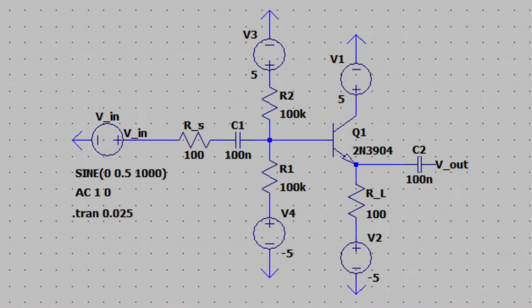For my schematic, as you can see above, I decided to use a BJT transistor because this circuit requires a higher Gm that a MOSFET can simply not provide. The amplifier topology I decided to use was a common collector because a common collector has a good behavior as an output stage and it meets the input signal swing requirements.